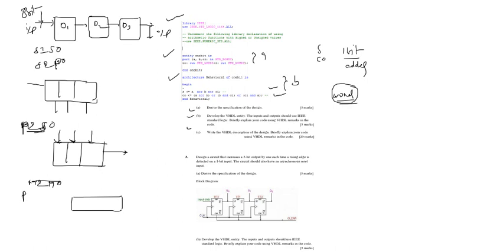Another one is parallel in parallel out, means parallelly we are inserting data and parallelly we are extracting data. So these are the 4 different classifications: single input single output, single input parallel output, parallel input serial output, parallel input parallel output, SISO, SIPO, PISO, PIPO.